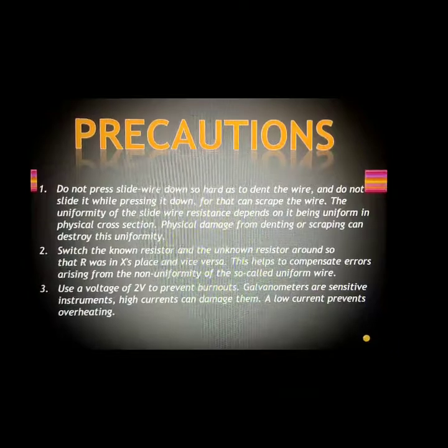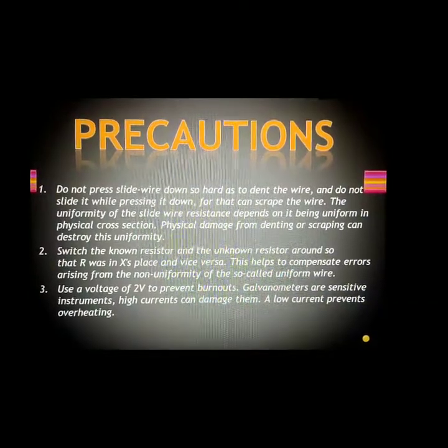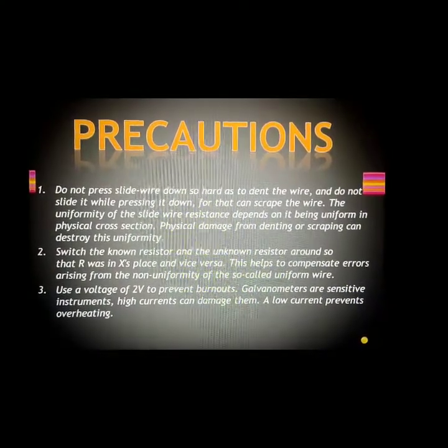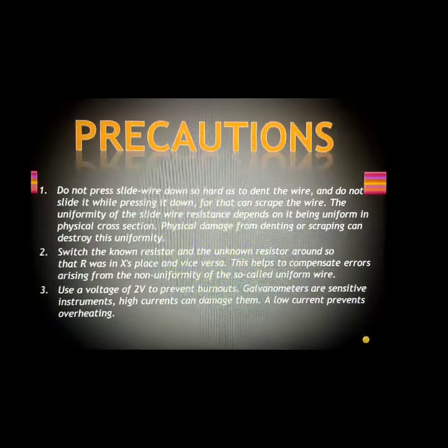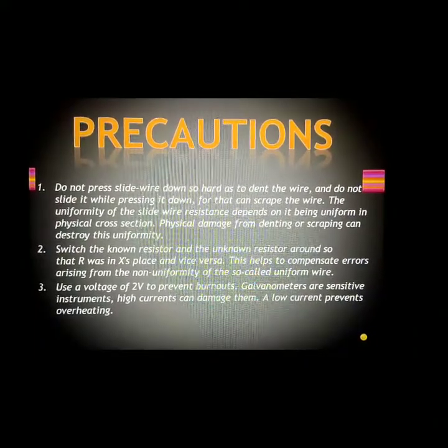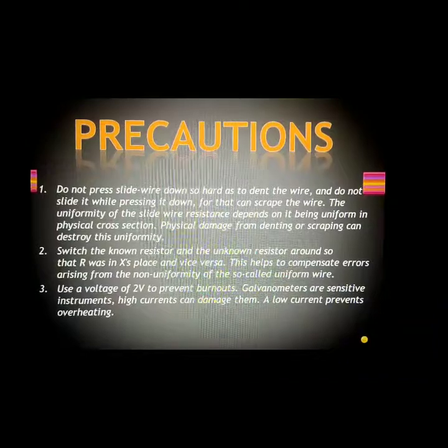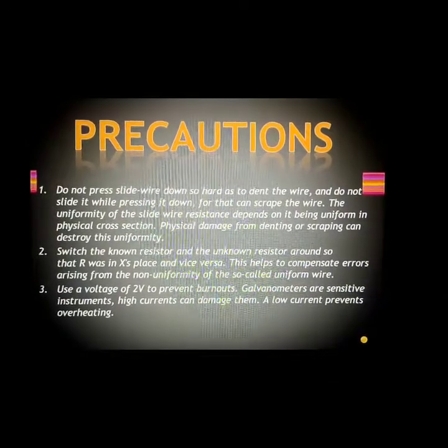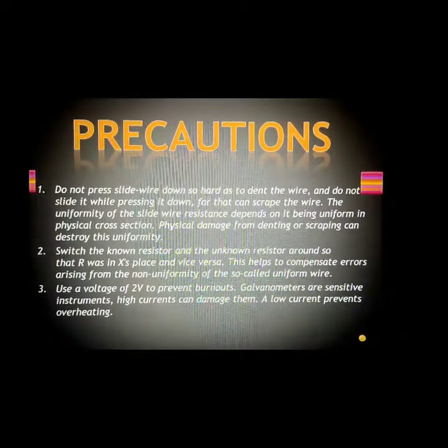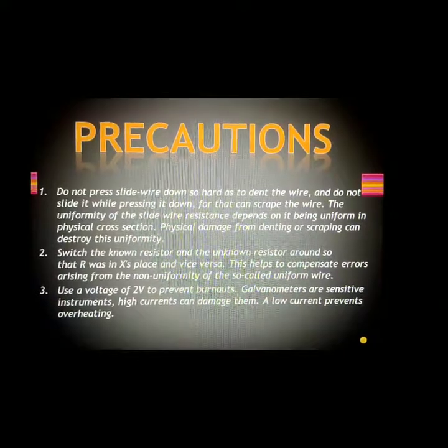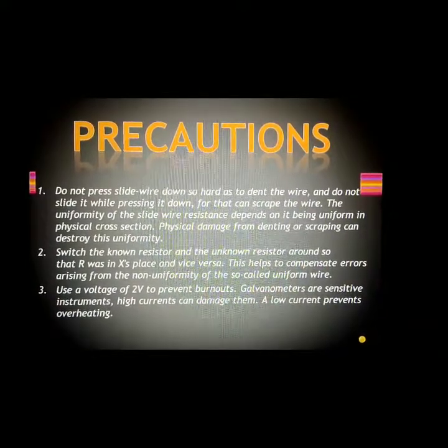You would have to keep in mind the following precautions. Do not press the slide wire down so hard as to dent the wire, and do not slide it while pressing it down, for that can scrape the wire. The uniformity of the slide wire resistance depends on it being uniform in physical cross section.